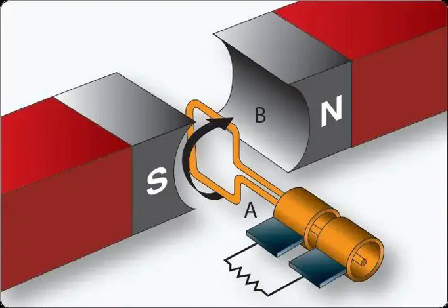The direction of the induced EMF alternates as the coil rotates, which is where the commutator comes into play. As the coil reaches a certain position, the commutator segments reverse the current direction in the coil, ensuring that the EMF always flows in the same direction in the external circuit. This creates a unidirectional current flow, generating direct current, DC, in the external circuit.